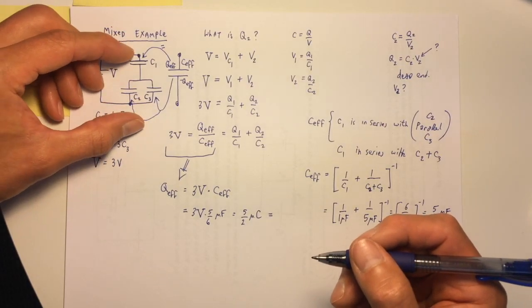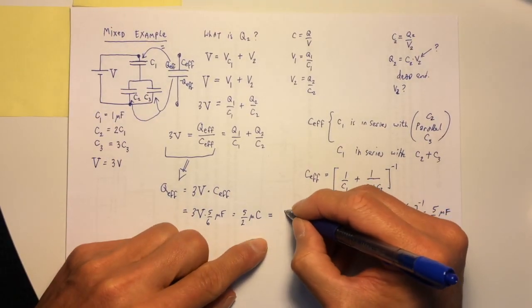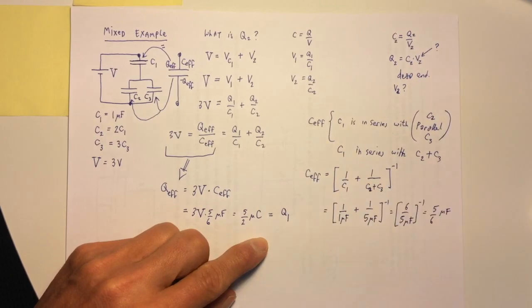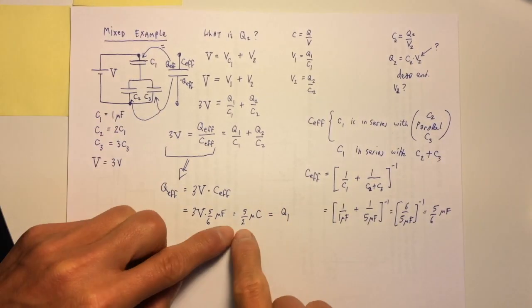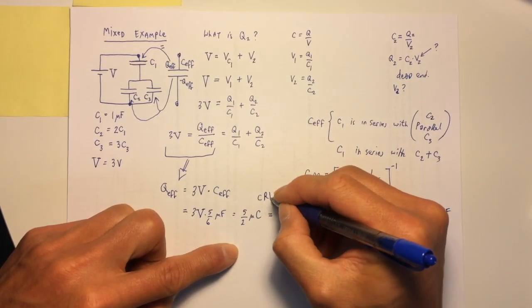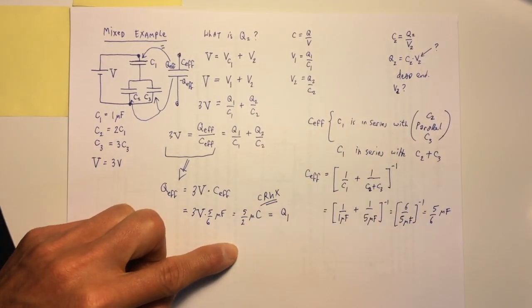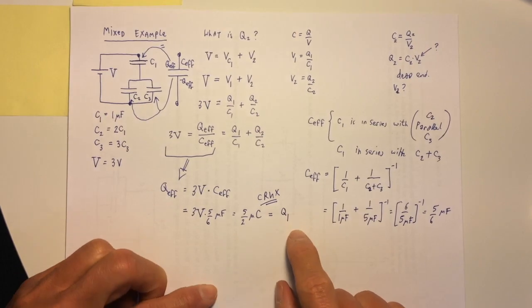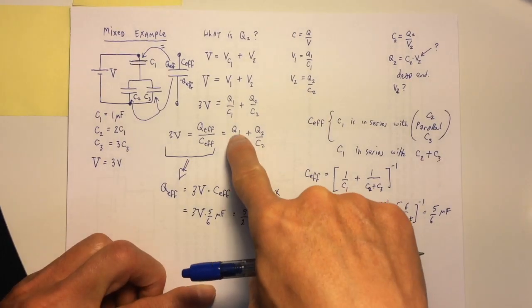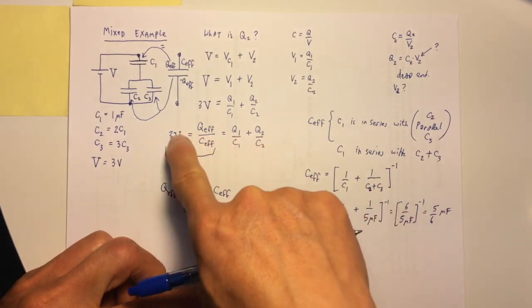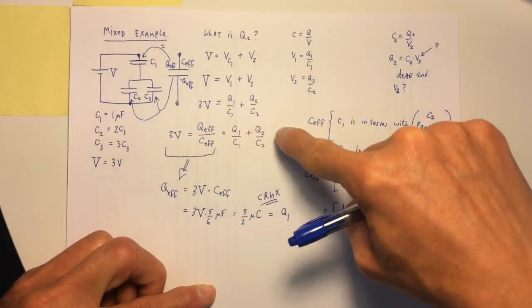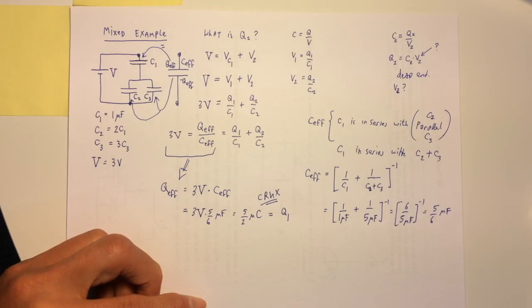Okay, so what I just showed you is that this is also, thinking about charge, the charge separated over capacitor number 1. And this actually is the crux. This is the crux decision to make, because once I say that I know Q1, now if I look at this expression, I know everything except for Q2.